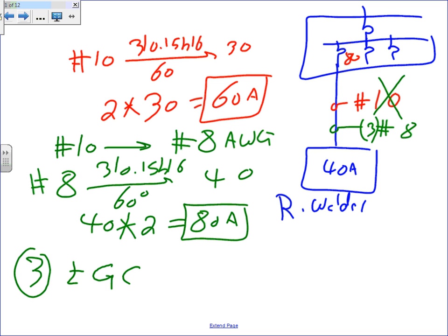But here's the chance that you're taking. Every time you start your welder, the 60 amp will trip, because ultimately they're in series. Yes, they're far away from each other, so there will be some buffer between them, but ultimately they're seeing the same amps coming into the circuit. That's why I hate that option. There's a solution with adjusting the circuit breaker, but really the best scenario is one circuit breaker up to handle the inrush and up the cable so it can't be burned because of overloading.